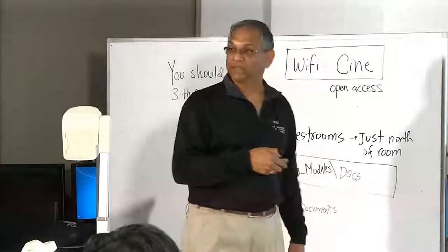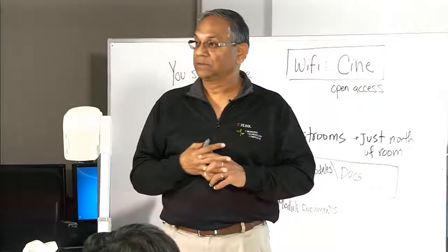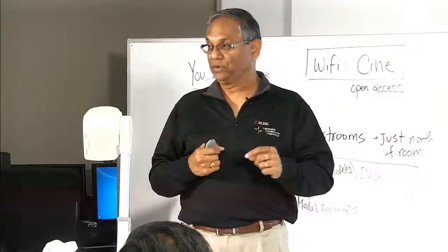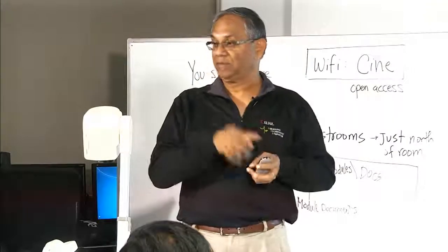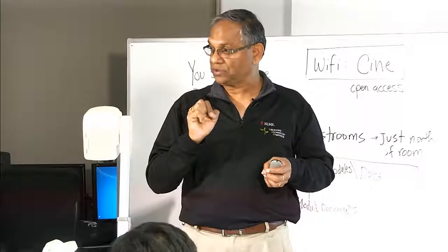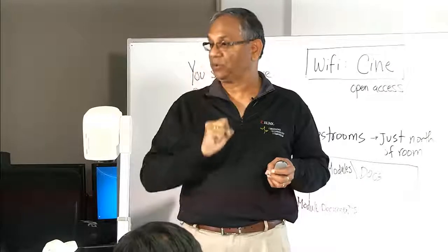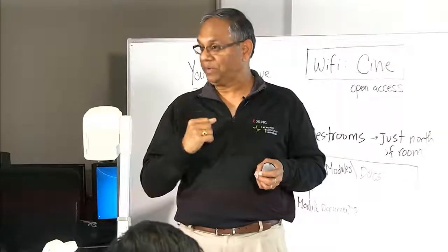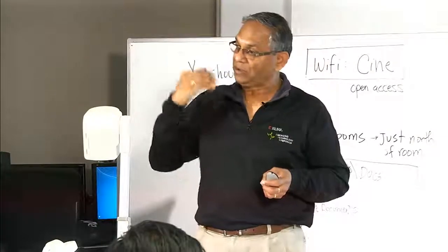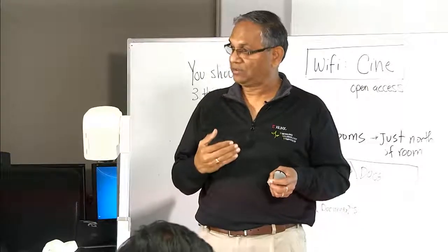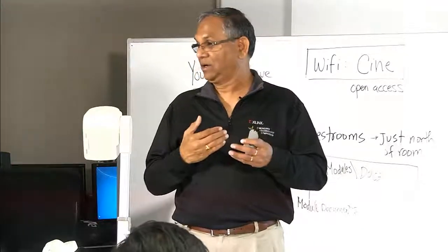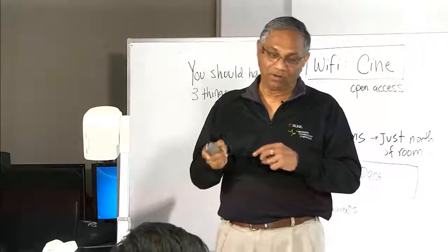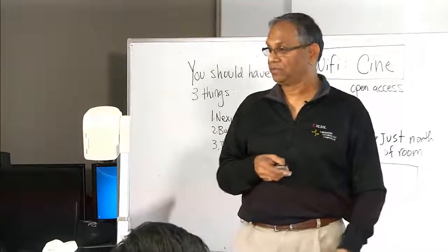Okay. Question. Yes, please. Where's the report you said in the report file that you're talking about? Where's that file? Yeah. So where is the report? When you start Vivado and go through, say, synthesis, in Vivado there is a tab called reports. When you select that report tab, there will be a synthesis report and a synthesis summary report both. Similarly, under implementation, depending on whether you have executed that process or not, you will have a report present or not, but it will be under that. Later on, when I switch to my machine, I can show it to you.